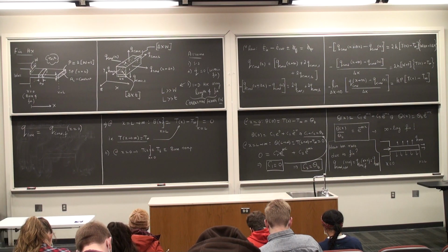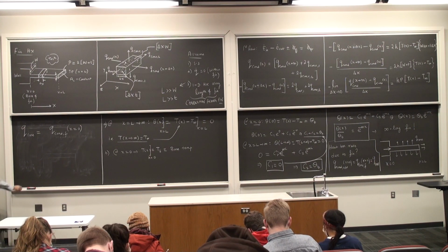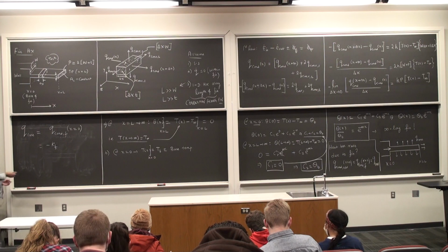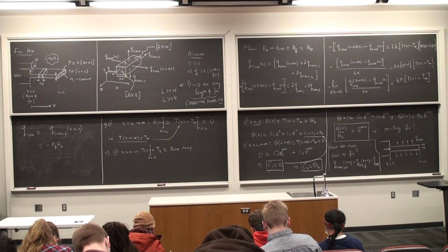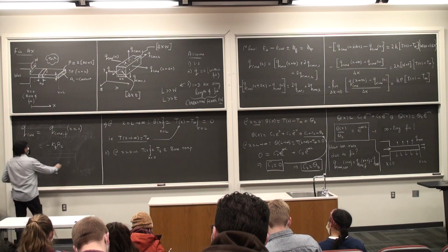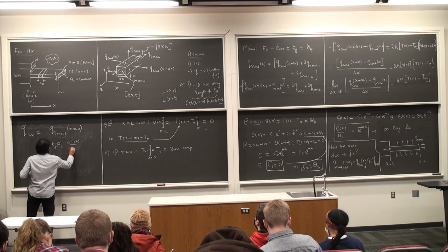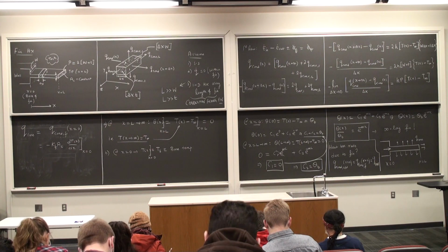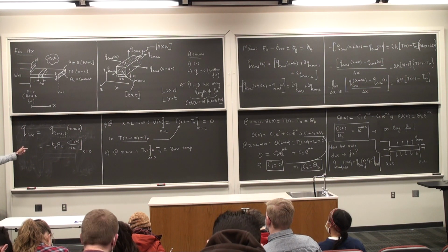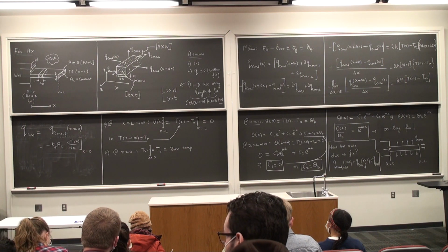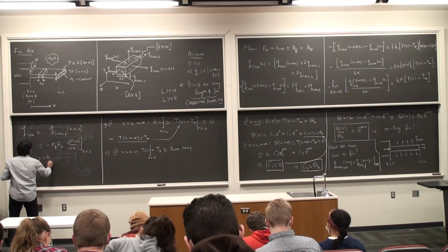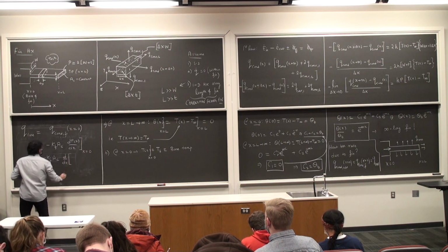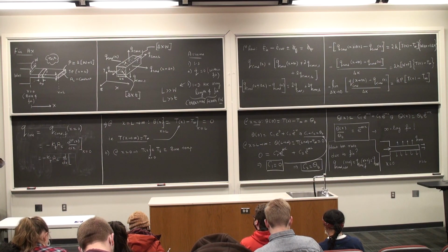at its base. Okay? For Q conduction, we are going to write the Fourier law here. So this is minus k of the fin, the conduction heat transfer rate, so the area of cross section has to come into play. So this is A suffix C. And then I'm going to have d by dx at x is equal to 0. dT by dx is the same as d theta by dx. Theta for an infinitely long fin is defined there, so this is going to be minus kf Ac d by dx of theta of x, which is theta b times e to the power minus mx.